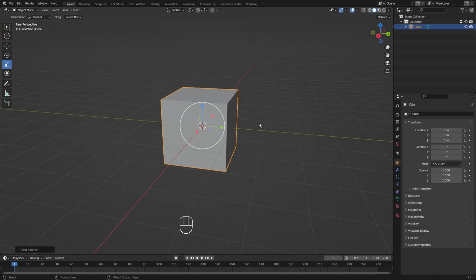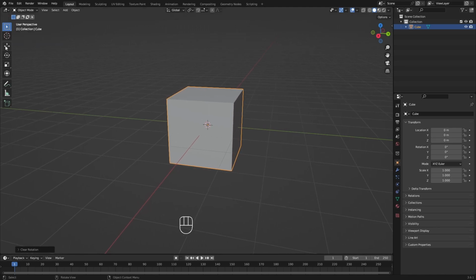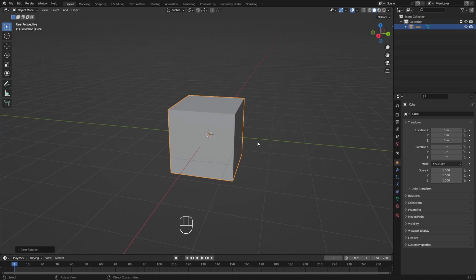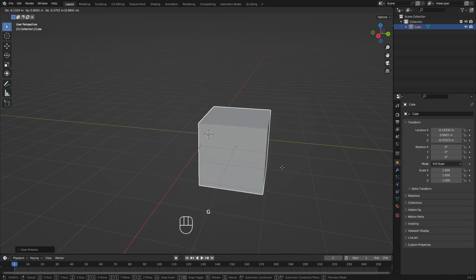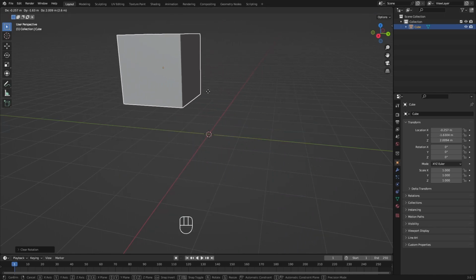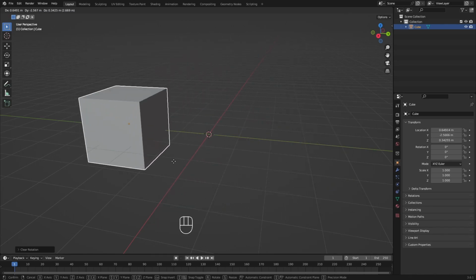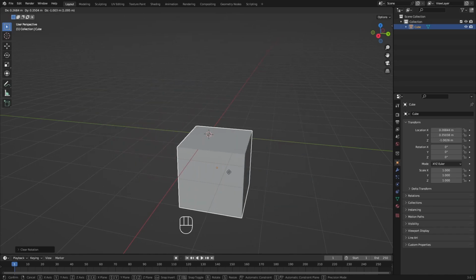We are going to learn how to use the shortcuts, because that's basically what I'm going to use throughout this course. Now I'm going to press W, so I go back to the select box, because we don't need these widgets anymore. We're going to use shortcuts. For example, to move, we use the shortcut G to grab. That's basically it. When we press G, the object gets bound to the cursor, so we can move it around like this.